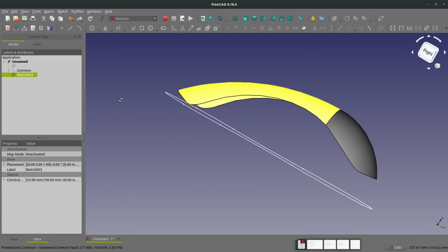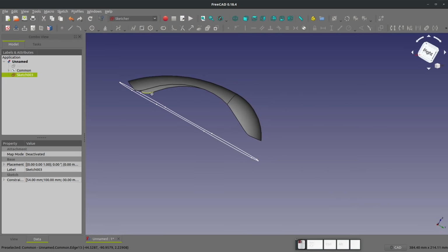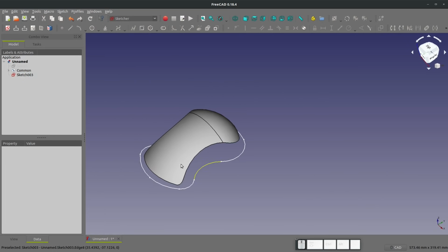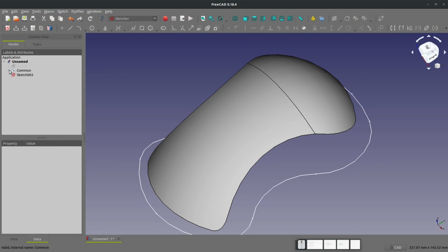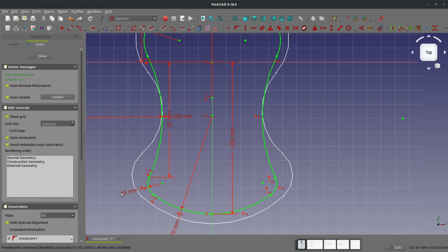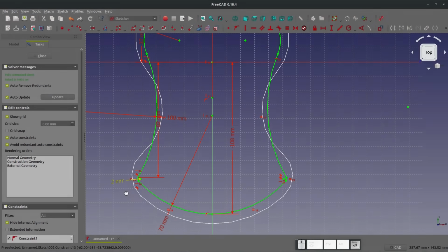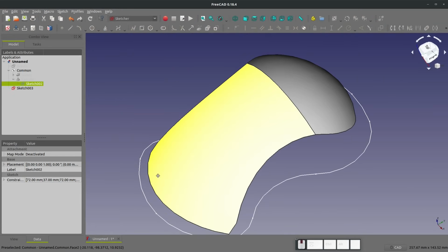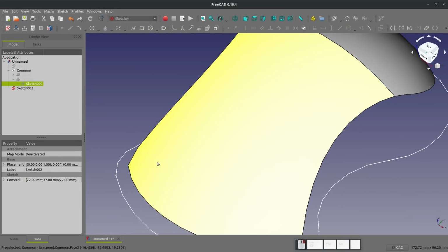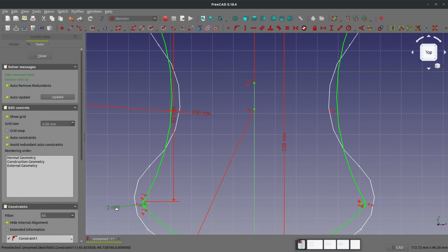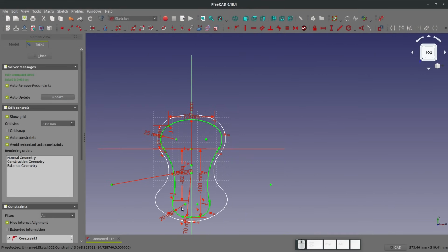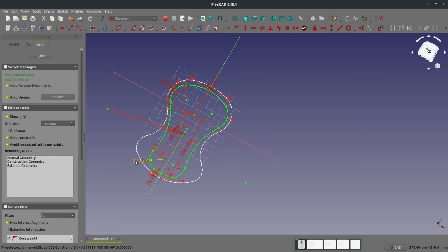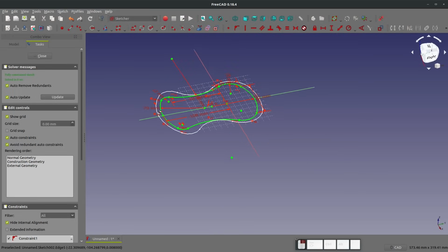And I notice that the corner of my mouse is drooping kind of low there. That might not look very realistic. So let's change our profile on our common just a bit. I'm going to go to my Extrude and edit sketch 002. Instead of 10, maybe we can make this real tight, like 2. If we close that, nope, that didn't help. 20, that gets a little bit narrow, so maybe I'll go 12.